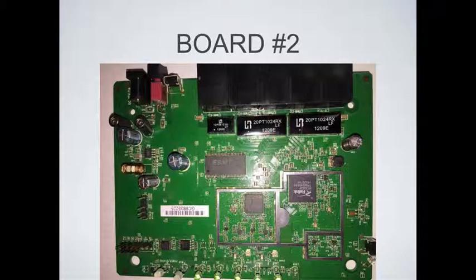Okay, so coming back, as we did in the last slide, by process of elimination, looking at big flat chips, we can assume that this might be the memory chip. These square ones are not. Something down here looks of interest, but I'm not really sure which one it is. But when you look closely, this has an MXIC, and this is an L4 something. I'm almost going to say this is probably not our chip. It might be this one, because I've seen after many times looking at a board that MXIC is a